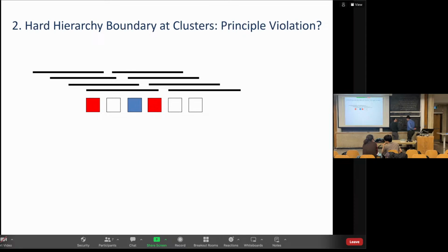Yeah, it's interesting. One thing I neglected, just because it's complicated, is if these aren't LUTs, like if I put a carry chain in, or in practice I actually have adders in here too. So in different modes, different groups of pins are swappable. And I also sometimes lose this output swappability. If it's a carry chain, I can't do it because swapping it around would break the carry chain. So for those ones, you can't swap them. And I think the fact that different groups, like it's not always 6 inputs that are permutable. Sometimes it's 5 because it's fracturable. Sometimes it's these 3 or these